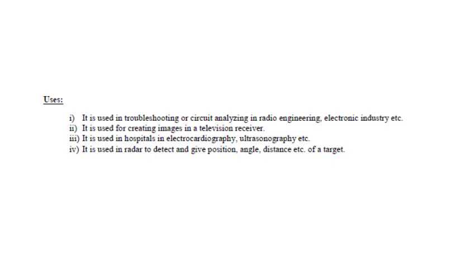Many applications are there. It is used in troubleshooting or circuit analyzing. As we discussed in the beginning, it is called the engineer's eye. You can see what is happening in the circuit. If anything is not working or malfunctioning, it can be seen here just by seeing the type of signal or distortion in the signal.